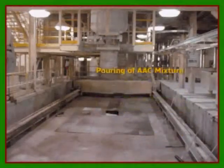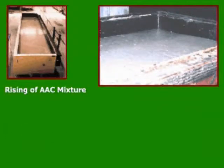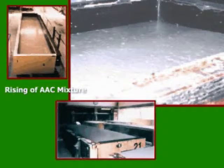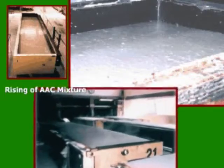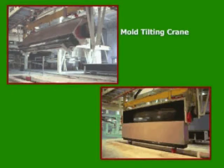Here we pour the pre-mixed raw material into our forms. In this curing room, the aluminum paste starts the reaction. As you can see in the top right picture, there is a 3 to 4 inch space. Then after 8 to 10 hours, the reaction is completed and the AAC in the green stage has risen to the top of the form. The cement reaction has also occurred, so the material is stiff enough that we can unmold the AAC.